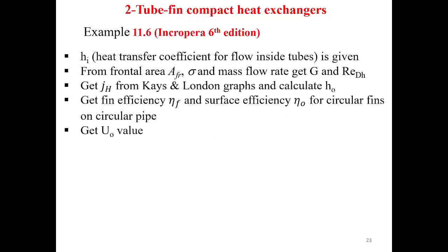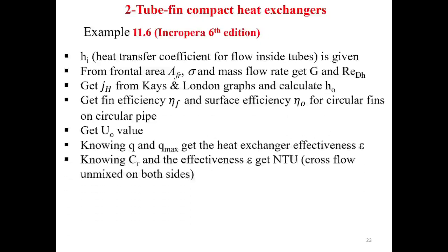The procedure that was followed in that example is illustrated here. We are not going through this because we have taken it before. The only thing that we would like now is to make a revision and build on that. So what you have to do in this example, for heating the water from 290 degrees to 370, and with all the information that is given for this surface, is that HI, the heat transfer coefficient for the internal flow, is given, which is 1500. So there is no problem with that.